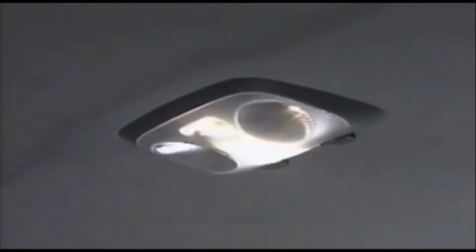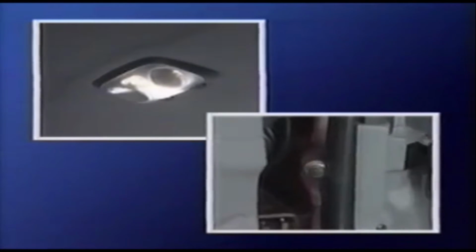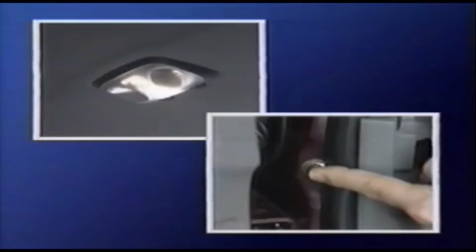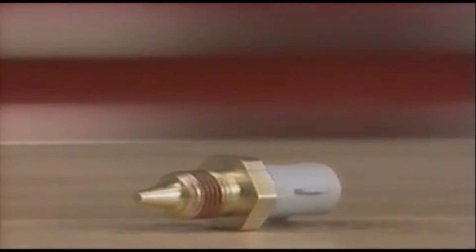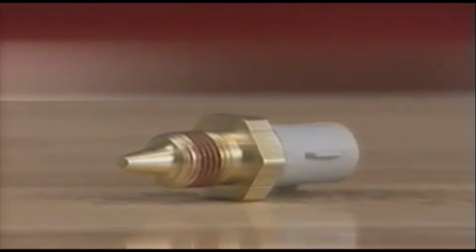Some circuits have the switch on the ground side. Dome lights in passenger cars, for example, usually rely on a ground side switch located in the door opening to complete the circuit. Also, in many electronic control circuits, ground side switching through motion and temperature sensors has become very common.